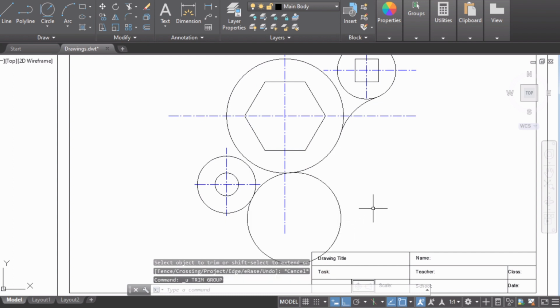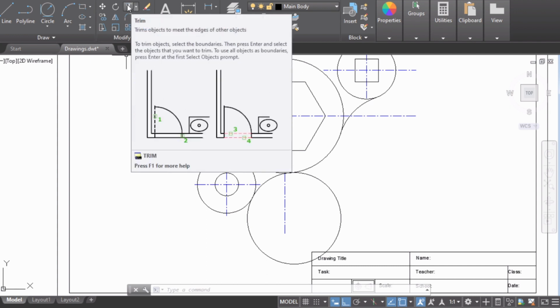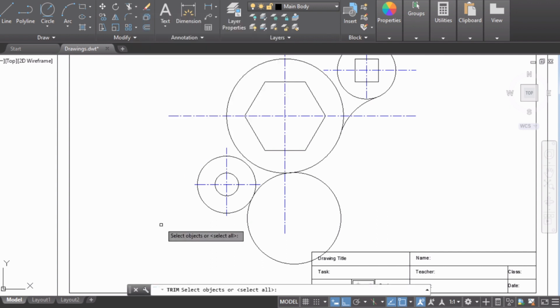You can see you are deleting this one by one, which is definitely a difficult task. So if you are in this kind of situation, I am not suggesting you choose this Control A and trim method. You should go for a professional way of trimming geometries in AutoCAD. The professional way is actually so simple. You choose the trim tool. This is the golden rule of trimming. First, find out which arc or which component you need to keep. So you need the connection between these two circles.